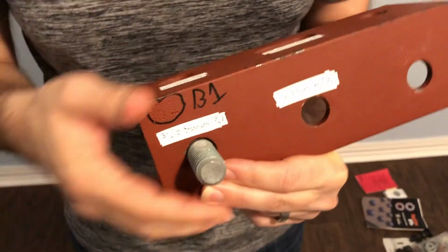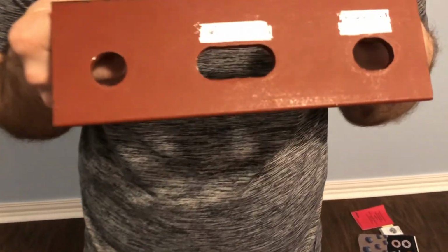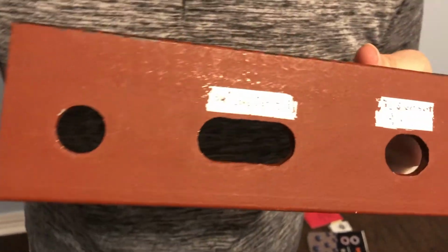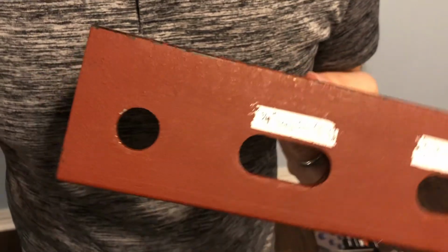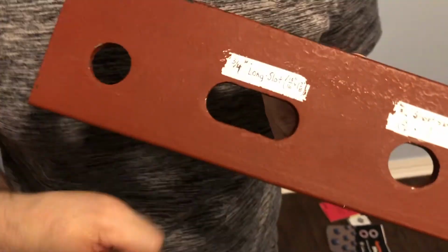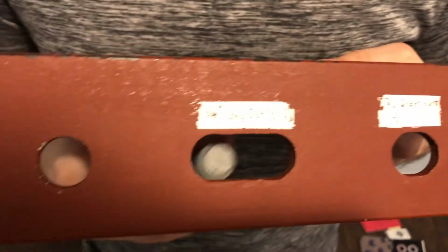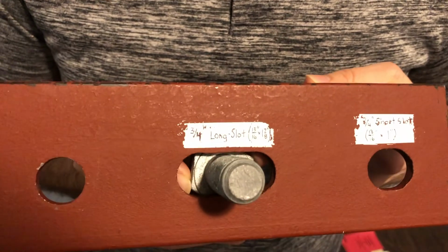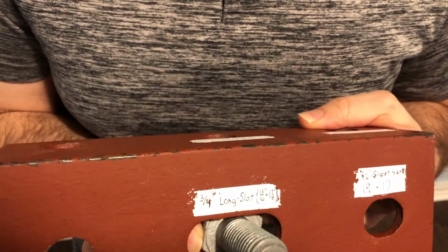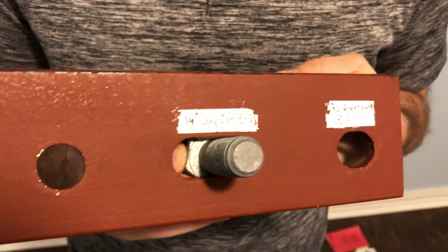Finally, the other two types of bolt holes are slotted holes. So slotted holes come into play, especially maybe in a bracing member where you want to have some ability to move back and forth. And so slotted holes look something like this. Now for structural connections, we're only allowed to build them so that the slotted holes are loaded perpendicular to the slot, so that we don't have a lot of that play in there, right?